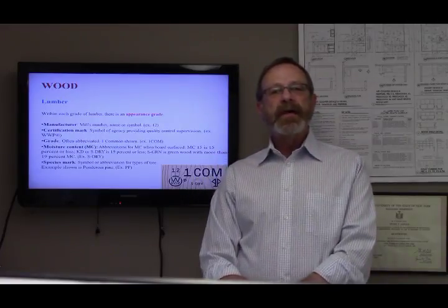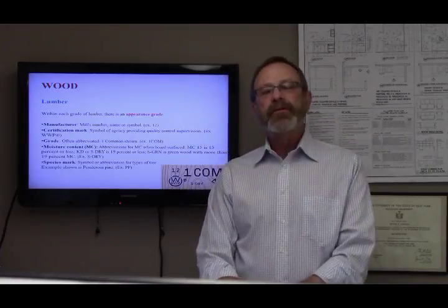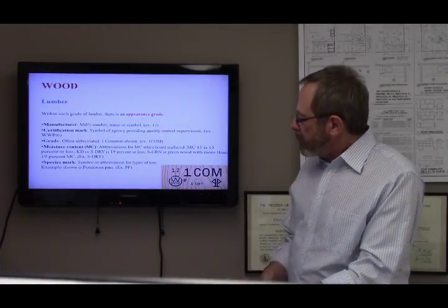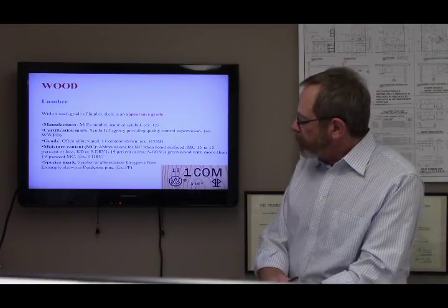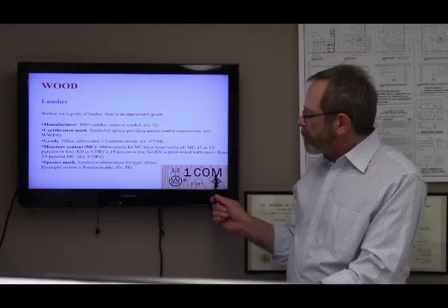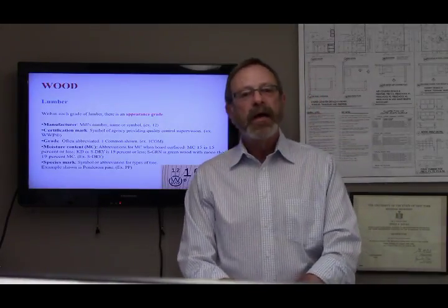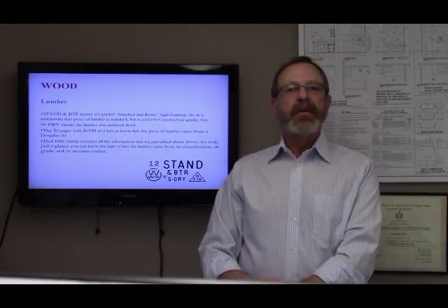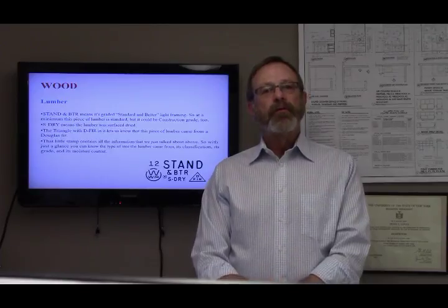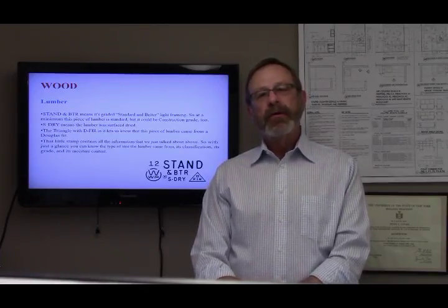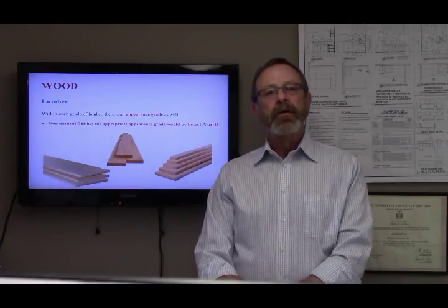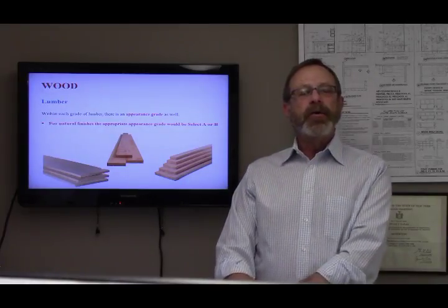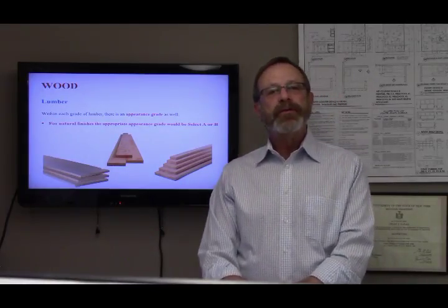It is then identified by a stamp and often inventoried by its grade and species. So here is a stamp designating the grade and species of this piece of pine, WP. It's number 1 common. Grade designations depend on particular defects such as knots. Keep your project final results in mind when selecting the grade of wood. Grade does not indicate consistency of color or grain pattern. Grading designation depends on the number of defects in a board. A lower grade can be perfectly acceptable, depending on placement and usage.